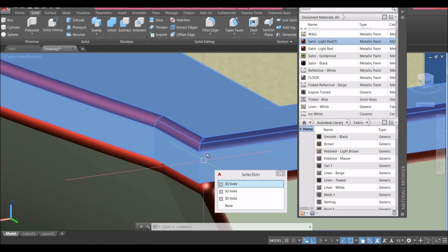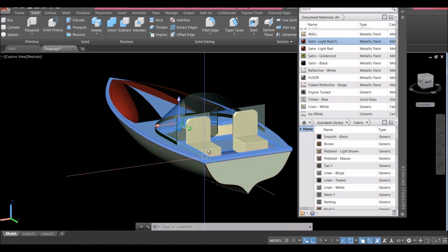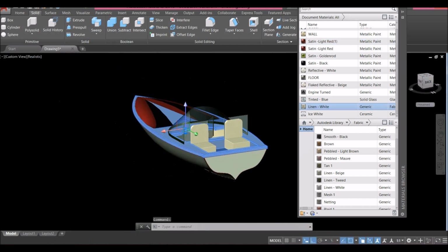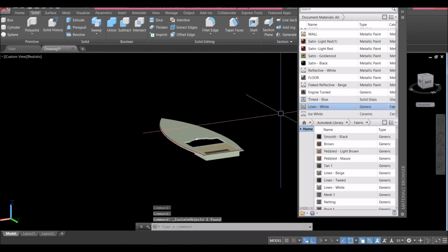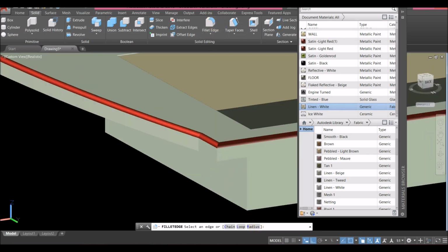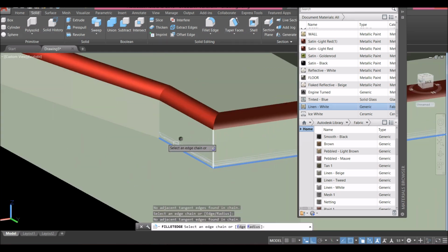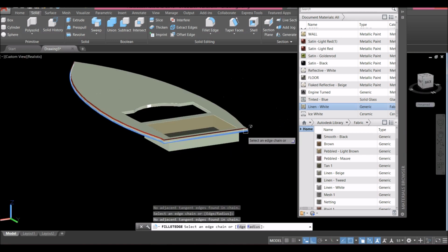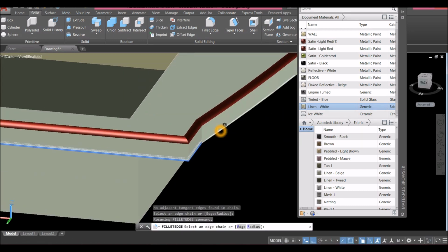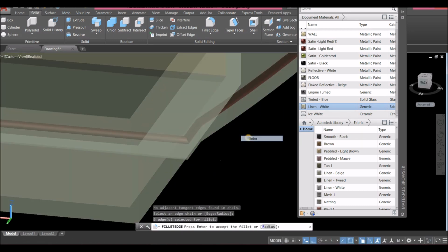And for this one, I'm gonna isolate because I have to fillet the edge there. Maybe the edge there. Okay, isolate and fillet edge, and I think I used 0.125 the radius and 0.25 chain option. Select this edge. Enter and enter again.